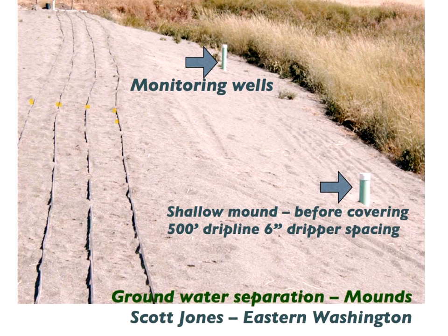The fecal coliform count in the monitoring wells was down to 0. And the beauty of this, though, which I'm sure you'll start seeing more and more of, is that it is a shallow mound. And it's nothing like as ugly as a conventional sand mound. And in this case, it is going to break out. There's no question it's going to break out here, into the wetland, but it's going to be clean water going into the wetland.